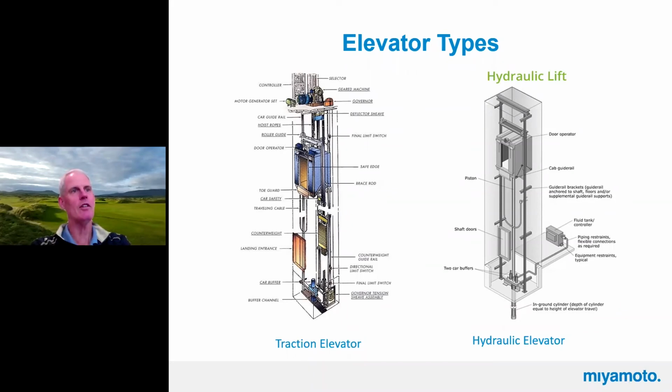No, Veronica's got a good point. I mean, typically you want them to do the shaft with shaft studs because they are a rated enclosure. So they need to have their own fire rating, and then the architect is going to have his own fire resistive assembly details that will meet whatever UL rating that they need. And our stuff all has to be within that and be coordinated. Hopefully it'll all work, but you do need to pay some attention to it because they may or may not.